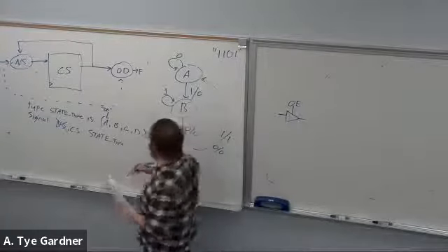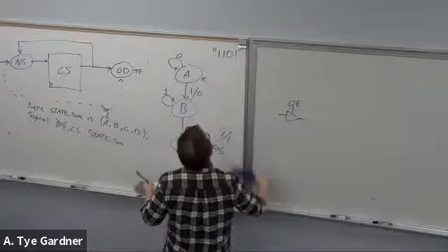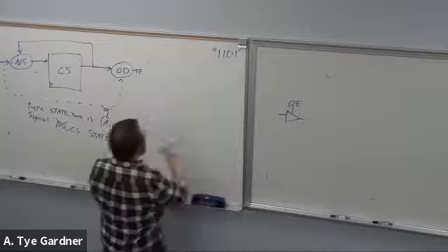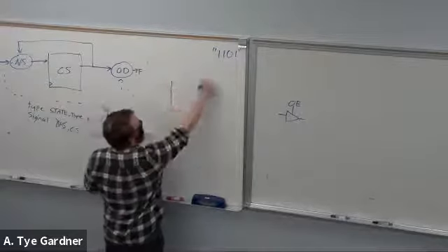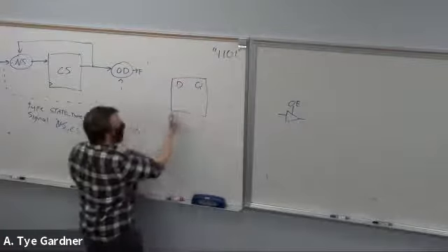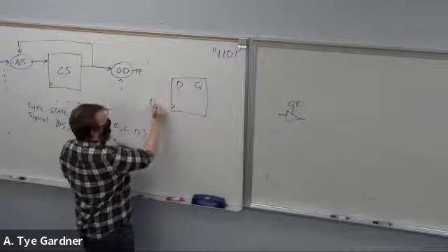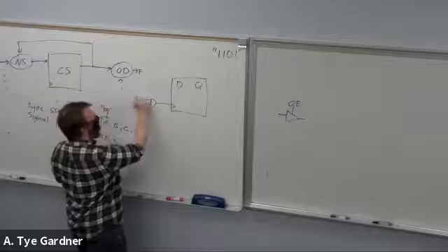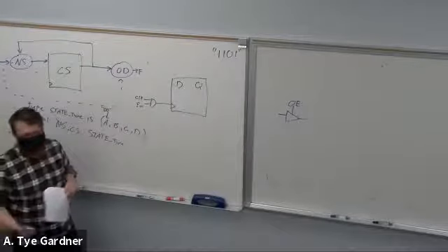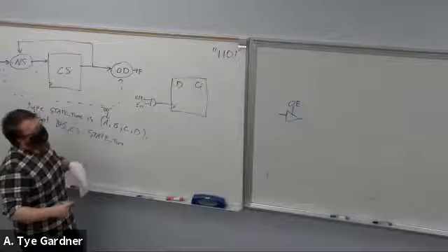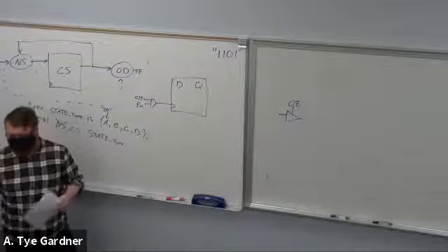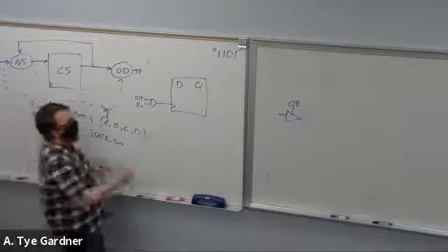Number 9 was just straight out of the notes, like I promised I would have some questions like that, right? Where I said, what is the right way to gate a clock? And the bad way is the AND gate that almost everybody got. Now, the right way, a lot of people remembered that it was something to do with a mux, but they forgot how to do it.